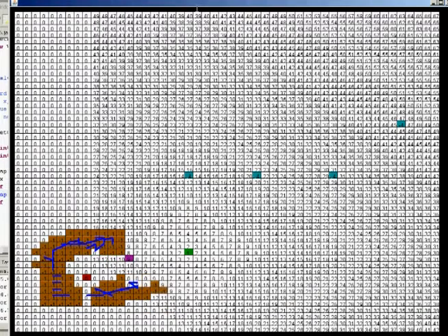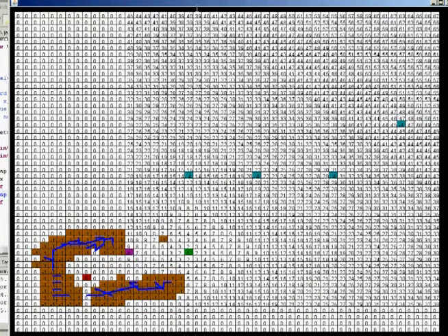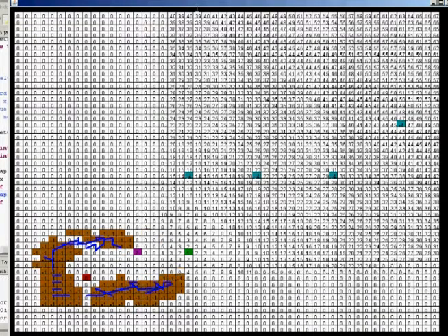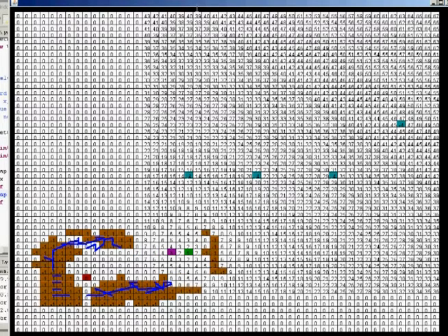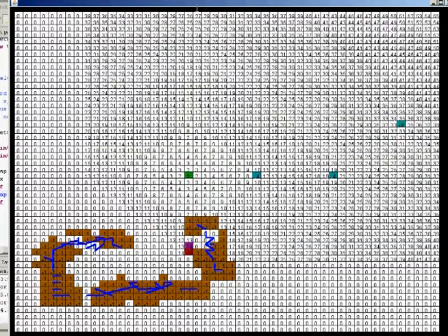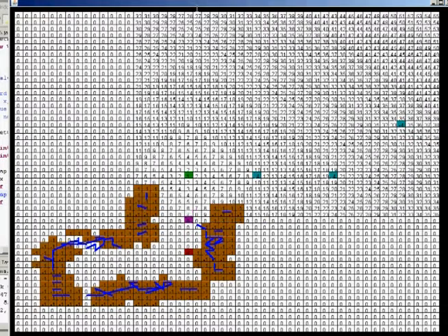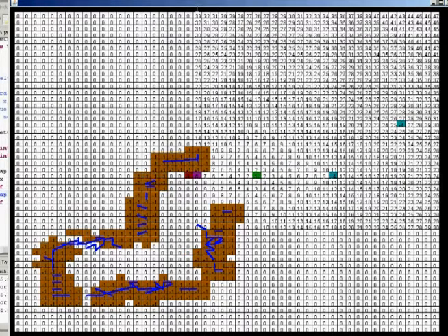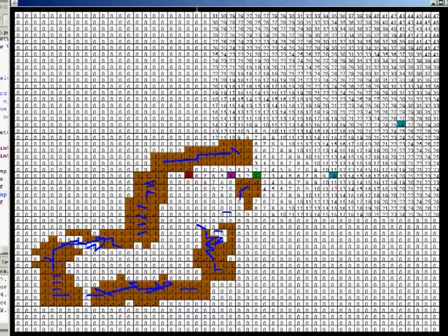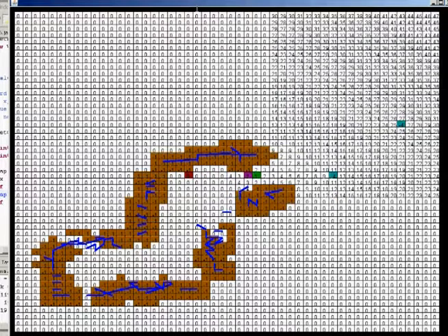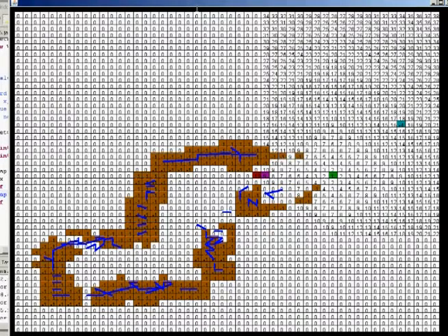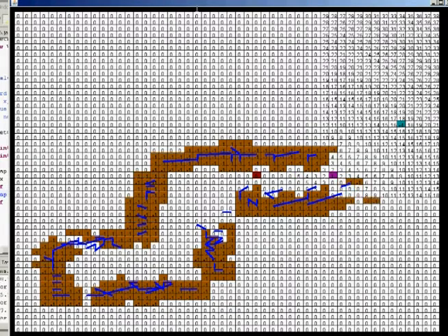So what I'm going to first talk about is odometry, how we use odometry to know where the robot is and what its orientation is. As we learned in the class, using the wheel speed and the encoders, we were able to figure out the odometry function from Lab 1. We use odometry to determine where the robot is and to return its position within the GUI. The robot is printed in purple if you look at the GUI. Next, we're going to be talking about generating the local map.